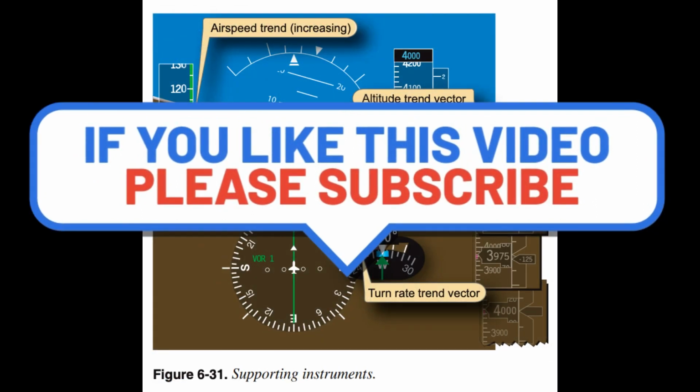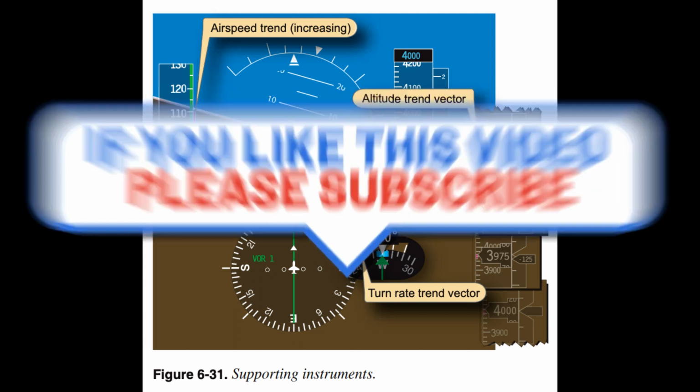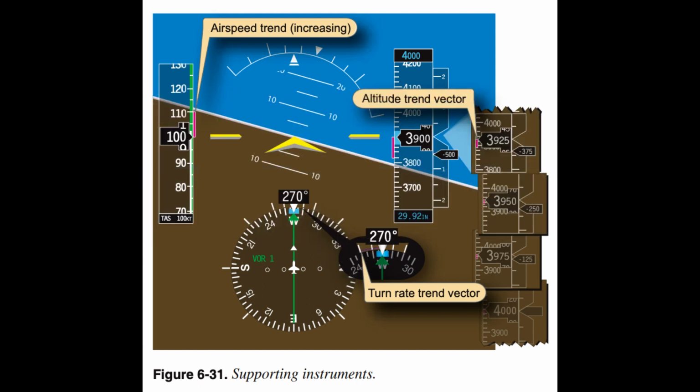When the pilot is maintaining a constant altitude, the primary instrument for pitch is the altimeter. As long as the aircraft maintains a constant airspeed and pitch attitude, the altitude should remain constant. Two factors that cause the altitude to deviate are turbulence and momentary distractions. When a deviation occurs, a change in the pitch needs to be made on the attitude indicator. Small deviations require small corrections, while large deviations require larger corrections.